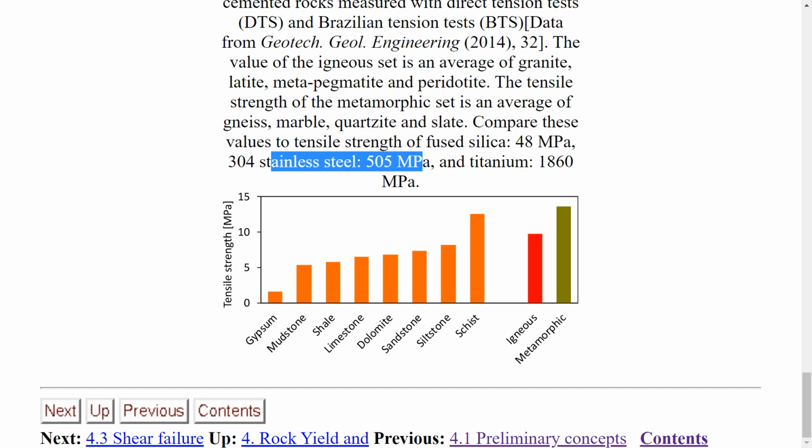And there is another example too that I have here in my box. So I told you, you can see, for example, typical sandstone, let's say 5 MPa, 750 PSI. In order to break it in tension, you'll need 750 pounds, more or less, for a 1 inch square. So I have an example here. And let me switch to the dock camera.